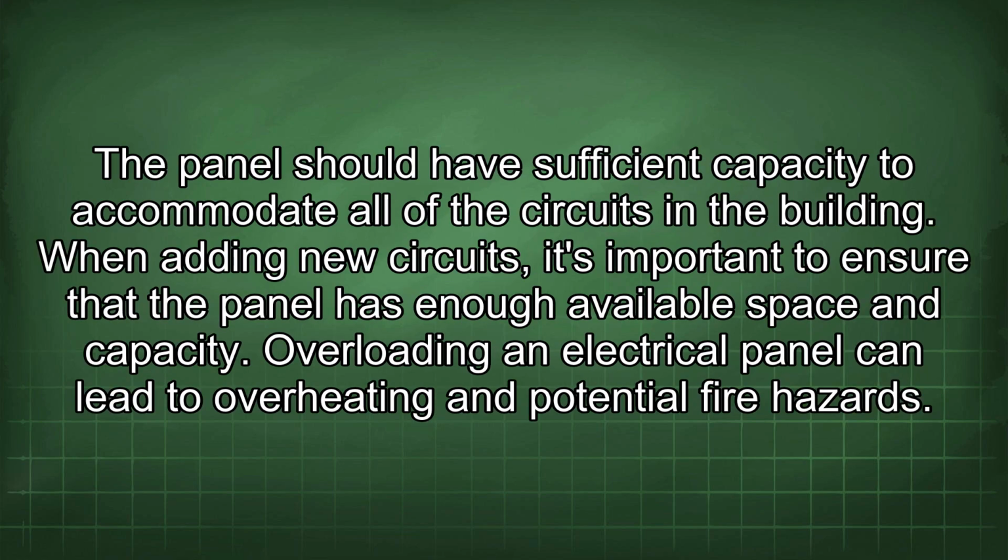The panel should have sufficient capacity to accommodate all of the circuits in the building. When adding new circuits, it's important to ensure that the panel has enough available space and capacity. Overloading an electrical panel can lead to overheating and potential fire hazards.